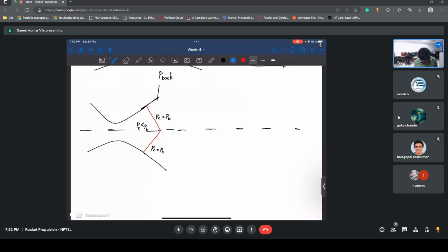Now what happens? The flow is going to go towards the central line, right? So it is going like this, and I put a shock wave which turns the flow, so it is going to go towards the central line. But I have to conserve the mass here because it cannot keep on going into the central line, right? So what it does is it puts on a reflective shock wave. That's what we call it, here, like this.